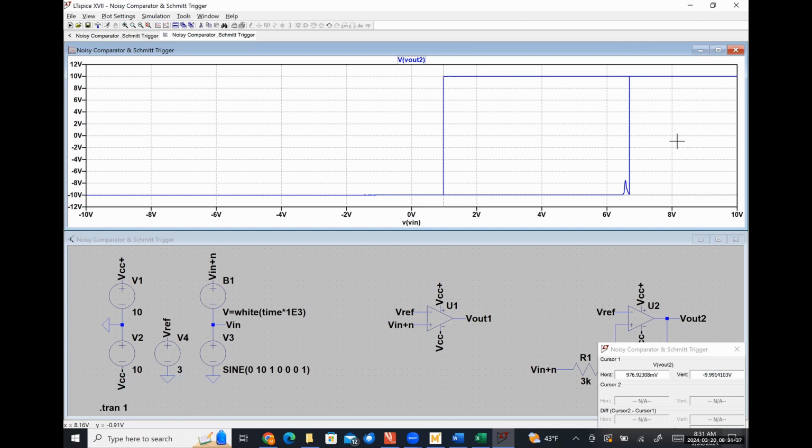If it's not, you'll never be able to exceed the upper trigger limit or conversely go below the lower trigger limit. I know that should be kind of common sense, but the reference voltage must be somewhere in between the upper and lower trigger limits in order for this kind of circuit to work. I'm mentioning that very specifically because if you look at your design projects, one of the first design project prompts I give you is designing a Schmitt trigger circuit to make a better analog to digital converter than the one that we designed in our last class meeting.